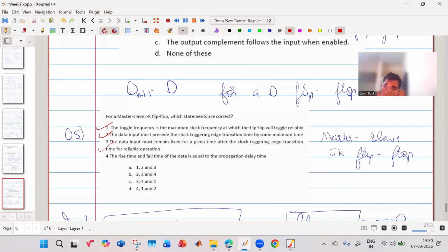Because we cannot have the case where the data input is faster and the output is slower, or the output is faster and the data is slower. That is not allowed. In these sequential circuits, we consider the same master clock, which is fed to all the modules, like we consider for the master slave clock. The same clock can either be enabled or disabled. You can create a positive edge trigger or a negative edge trigger, used for edge triggered flip flops and latches, or for level-sensitive latches.